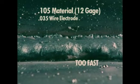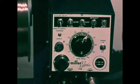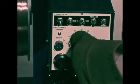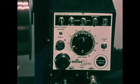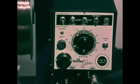The wire feed speed setting was simply too high for an efficient weld joint to be made in this thickness of material. Deliberately selecting a low wire feed speed of about 100 inches per minute will give the operator a welding amperage of about 75 amperes.